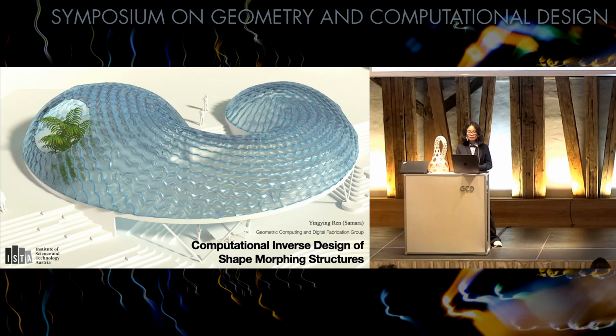Additionally, we need a minimal width of the fusing curve. Some of the models that we built, for example the neck brace, are currently larger than a human neck size, because our fabrication methods right now need the fusing curve to be 2 millimeters, so we cannot reduce the size of the model further. So definitely, I agree, this is still challenging, either scaling up or scaling down the fabrication. But I would love to talk more and explore later.